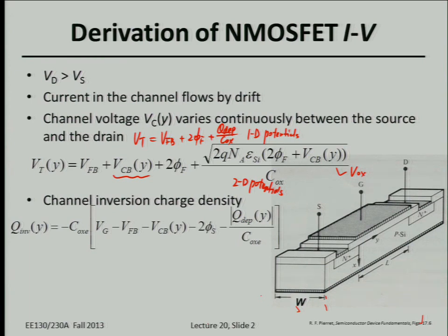So if you really look into the voltage drop across the oxide, because you always have the charge you generate from the gate, that's always uniform, right? Because the gate is kind of like a conductor. But since you need to use the charge on the gate to balance the charge in the semiconductor region, and that is non-uniform, you need to take into account the lateral voltage drop or potential difference. So you're expecting the voltage drop across the oxide will also depend on the distance you look into, right? It will be a function of y, okay? It will vary versus the distance, right?